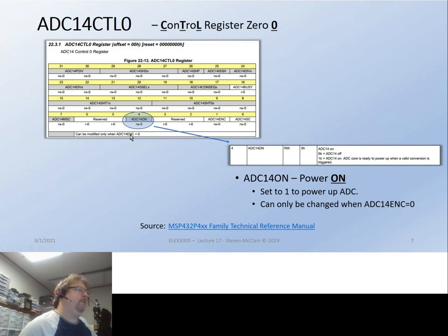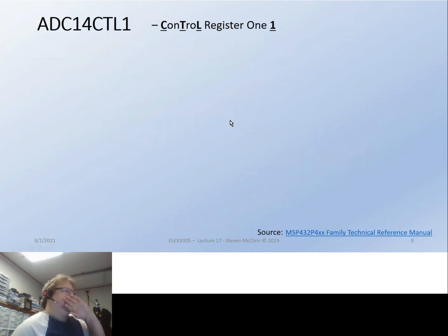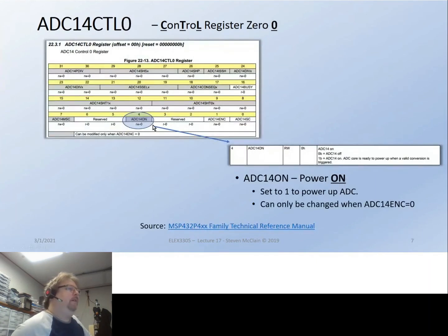And these gray ones are bits that can only be modified when this is set to 0. So basically all of them except for the start conversion and the busy flag, because you can't even write those. Well, you can write start conversion right in code, but that's it. And you probably don't recommend, like you said, always doing that control or enable. You can pop the clutch with your last write if that is truly your last write. But typically, I wouldn't re-enable it until I've done all the setup for whatever I was going to do.